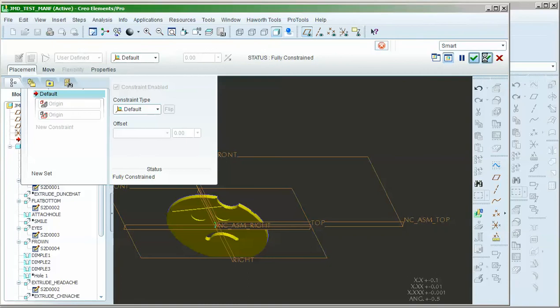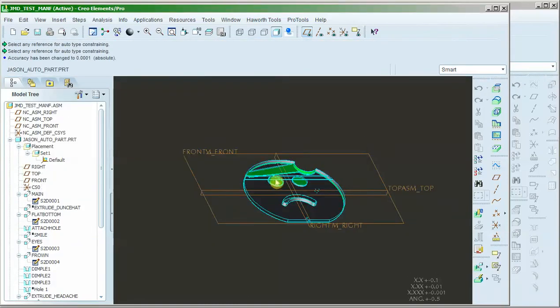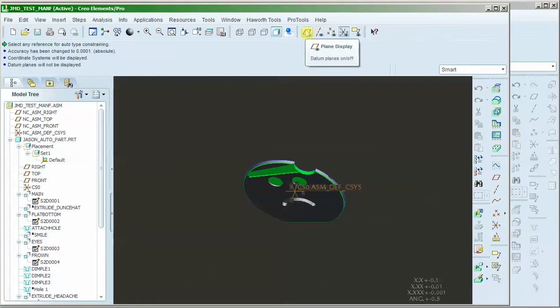But Kevin, why is it that it doesn't really matter where your coordinate system is? A lot of what we're going to do with this example is going to be controlled in our post processor. Speeds and feeds, and also the coordinate system for the machine will be controlled by that specific post processor. Okay, so as we go, you'll see that I'll be setting some feeds and doing things like that. Those aren't necessarily going to matter once it gets through post processing, but we'll do that so that you can see the toolpath play live, which is really very important. It's a good way to debug.